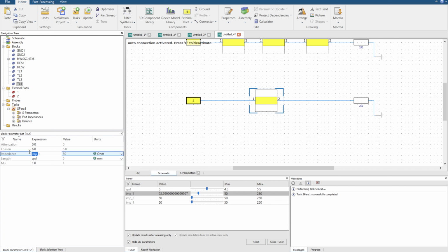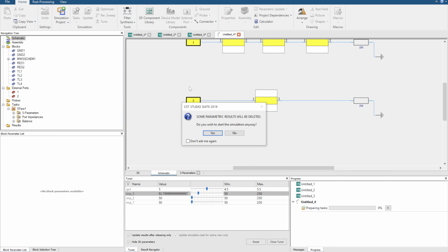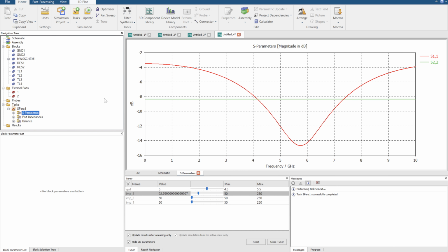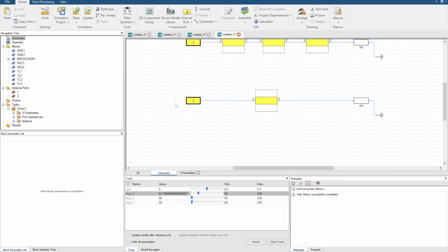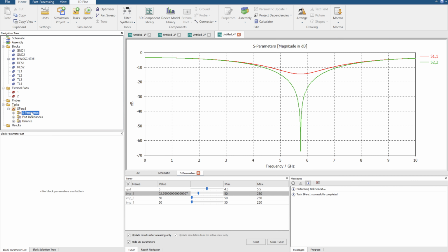So I know what the impedance is going to be. It's going to be similar to the last video, 50 times 250, close bracket, square root, 0.5. And the quarter wavelength is going to change, perfect. I'm going to click update. Yes, I would like to update it. And I didn't. See what happens when I don't state the block dependency. So constant because I closed the last one down. So constant, and update. Let's check everything. Perfect. So here's our perfect ideal scenario.